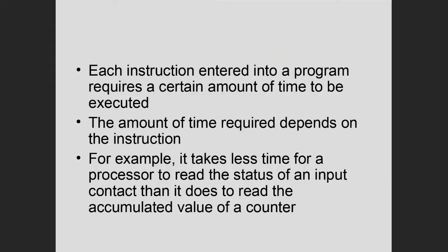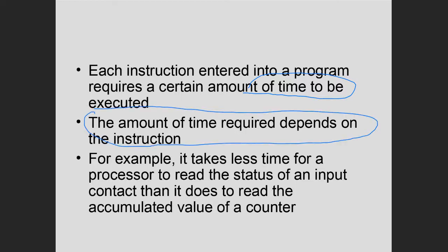So this idea of scan time. It takes time for each instruction to be executed. So the amount of time depends on the instructions you use, how many you use. Right here, it takes less time for a processor to read an input that's either open or closed than it does to read the input of a counter. So it takes time. This idea of time is important. We'll talk about why it's important in just a second.